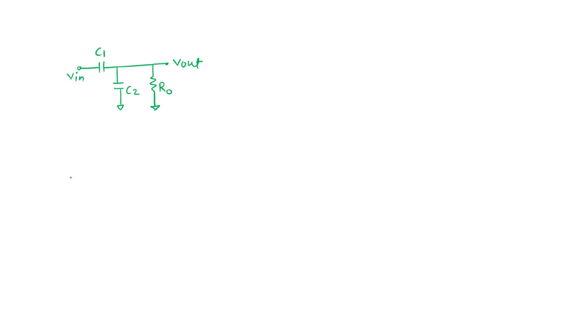When we calculate the pole, we will see Z1 equal to minus Z2. This is the fundamental. But what we are seeing here, when we make our V in 0, which is the first step, and we short it, what will happen? Actually, the circuit will reduce to two capacitors in parallel.